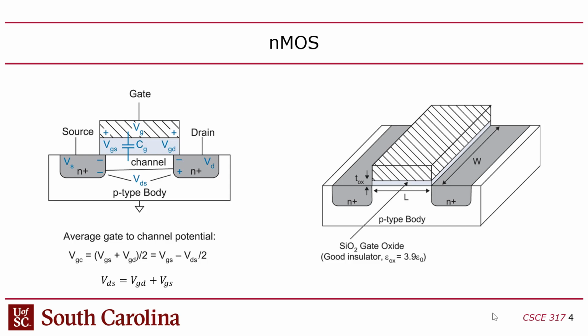So when you hear someone say, oh, that chip is an 11 nanometer process, or that's a 7 nanometer, oh, Intel can't get the 7 nanometer process working. We've been waiting 3 years. What was wrong with their fabrication? That's what that refers to, the L, the length. You want that L to be as small as possible, because the smaller your L is, the less distance the charge carriers have to travel when current is flowing between those.